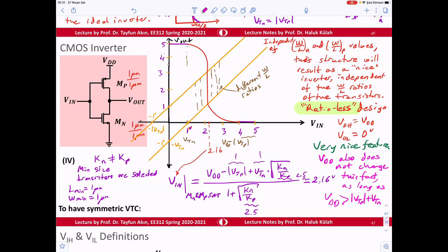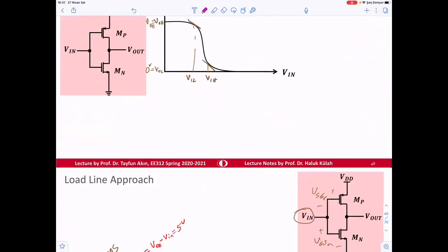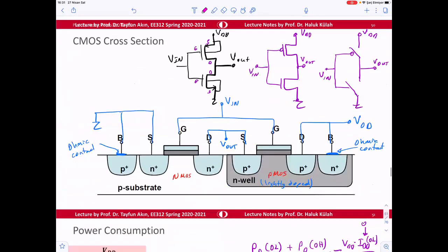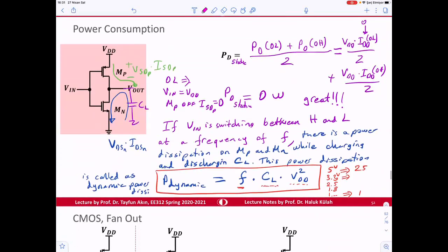So let's say for 3 volts, this will also work properly. So for devices here, if supply voltage is dropped to 3.3 volt, this will work. But maybe at 1.8 volt, threshold voltages VTN and VTP should be selected small for proper operation.